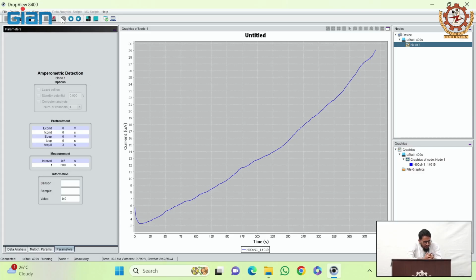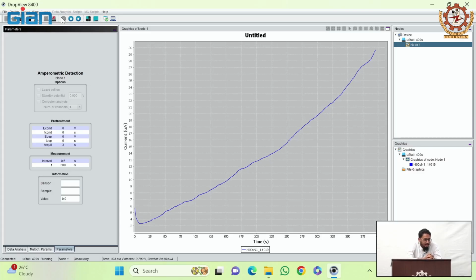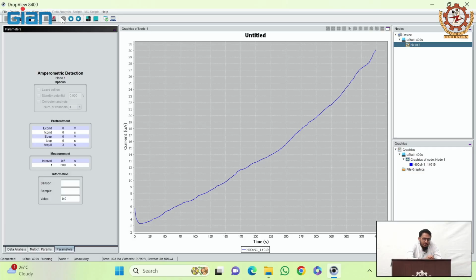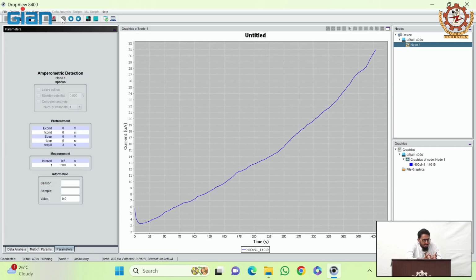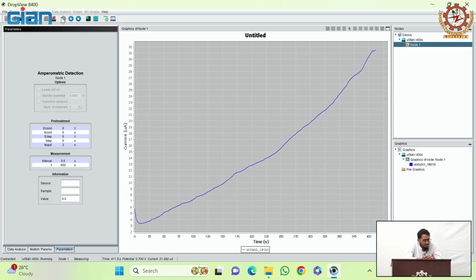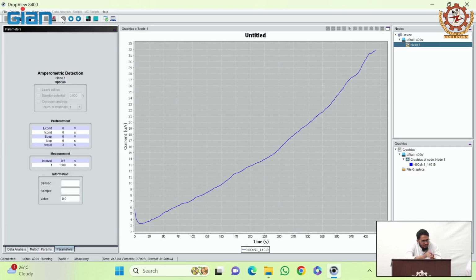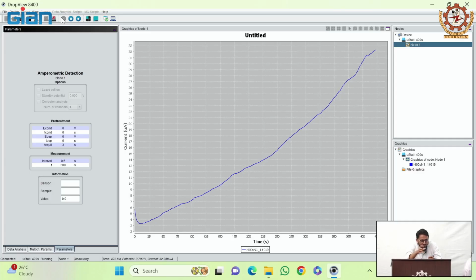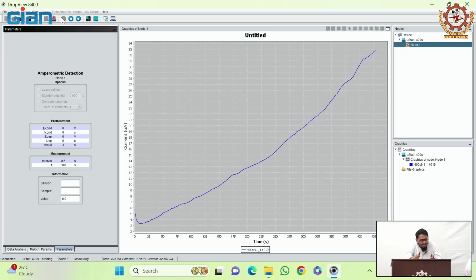The sensors that I passed around are called factory calibrated sensors. They do the calibration step in the factory, and they know exactly how long the sensor will last without calibration, and within what range the sensitivity lies. Once you implant this sensor inside the body, there will be immune reactions as we discussed earlier, and the sensitivity will decrease with each day. They know how to model that relationship from day 0, day 1, day 2, day 3, how much sensor degradation is happening, and accordingly they adjust the sensor reading.